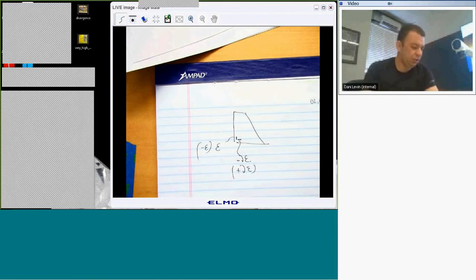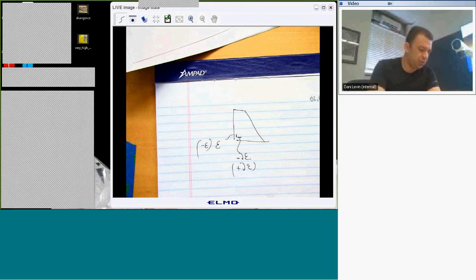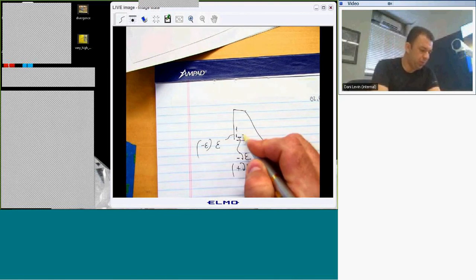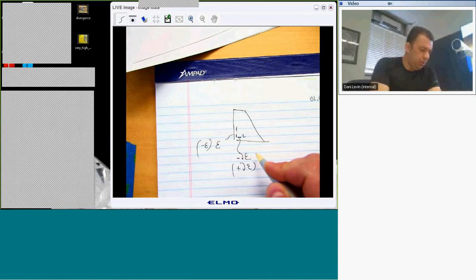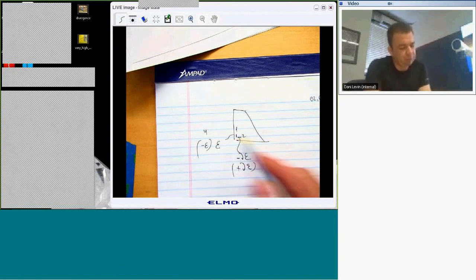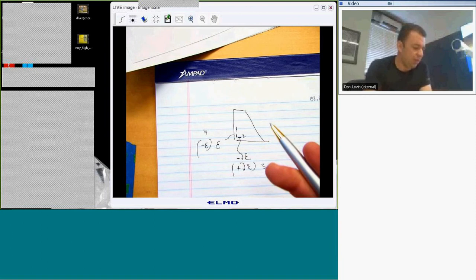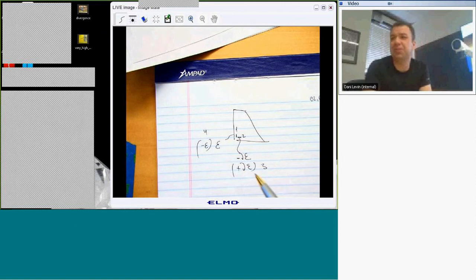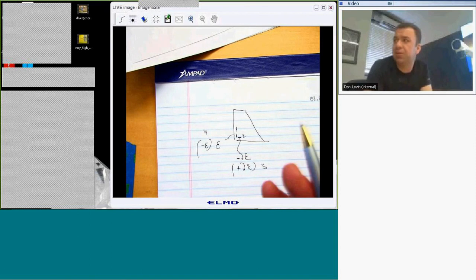So you can wire your gauges. Let's call this 1, 2, 3, and 4. This is the standard wiring for a bending bridge. The advantage of the full bridge is, for example, the temperature effect cancellation. I'm not concerned with any drifting in this particular case.